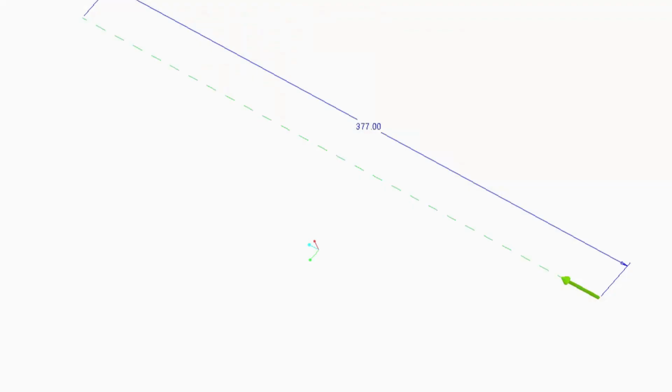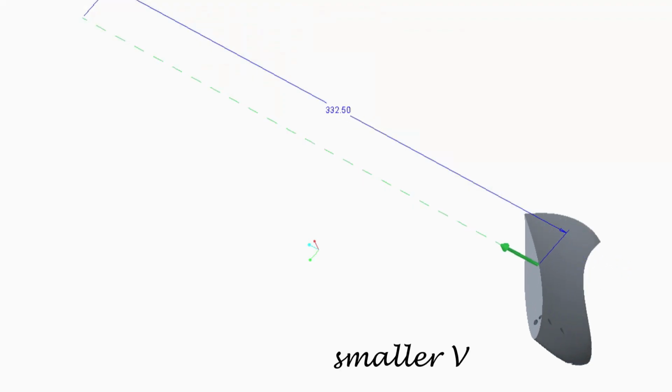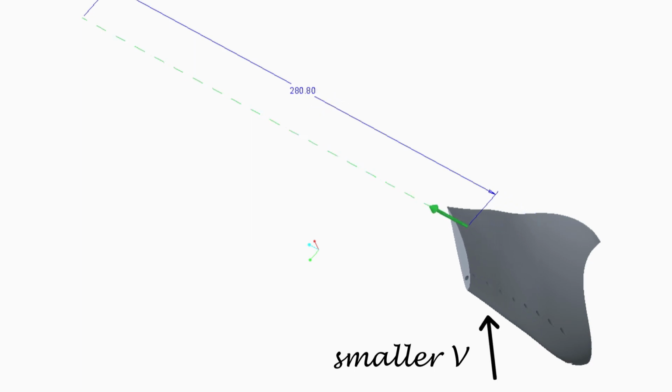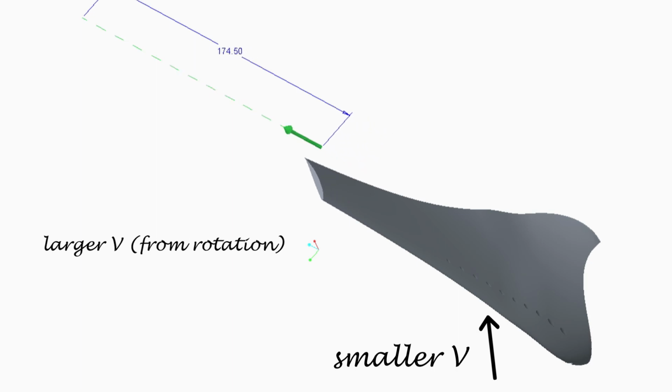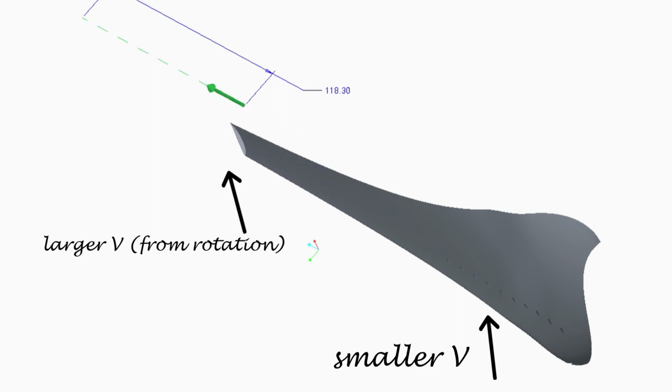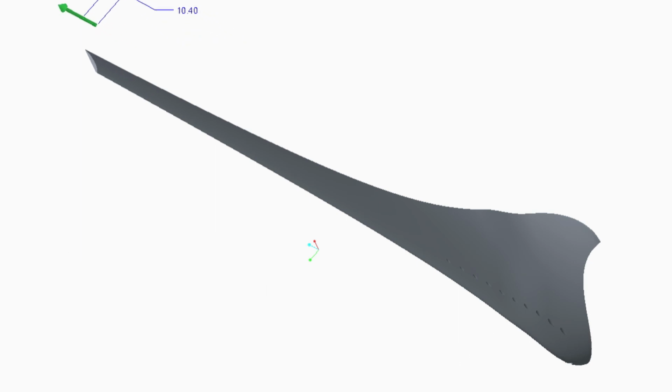Although the blades are rotating at the same angular velocity, the further that section is from the hub, the greater the speed at which it is spinning. As a result, different parts of the turbine experience different incident air velocities in terms of both speed and direction. In order to maximize the efficiency of the blade, we twisted and tapered our turbine blades from the root to the tip according to the angle of attack, which maximizes lift and minimizes drag for each section.